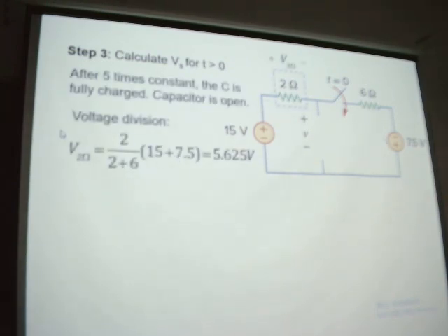We also can use voltage division, right? These are in series, so the total value is 50 plus 75. And here the voltage should be the value of the sum, and we get the value. It's easy, right? So our V infinity, we can use 15 minus this one, or we can use the value here. You can take both sides, it's up to you. You can calculate the V from this loop, and you also can calculate the V from this loop.